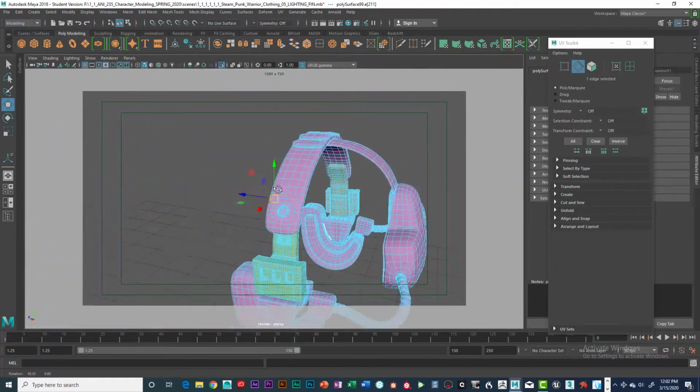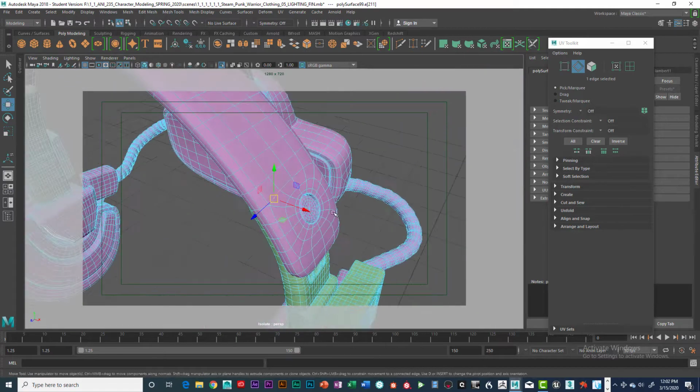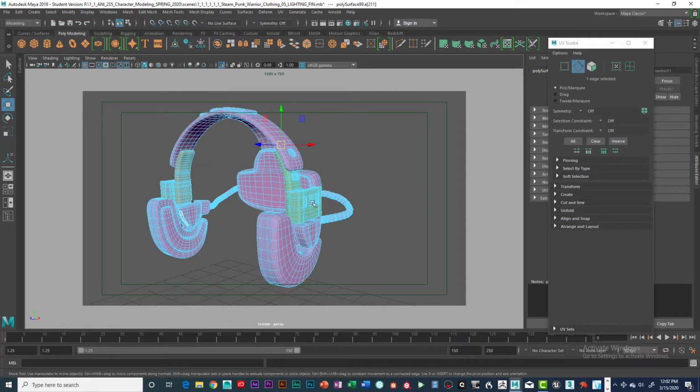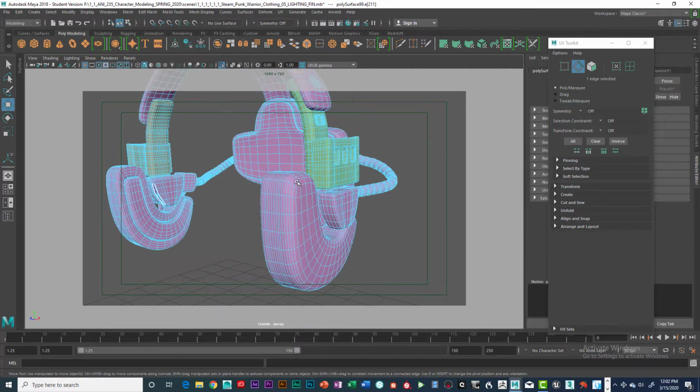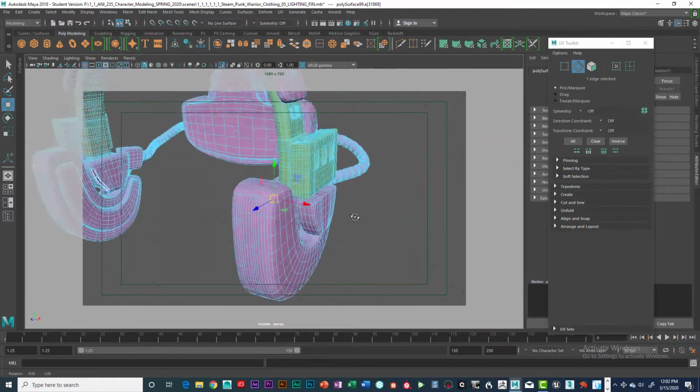You can see how that's rotating around it because it's found its pivot point. That's how focus works. So if you're UV mapping and you get stuck and you're not rotating the way you want to, just hit the F key, and that will rotate around that particular object.